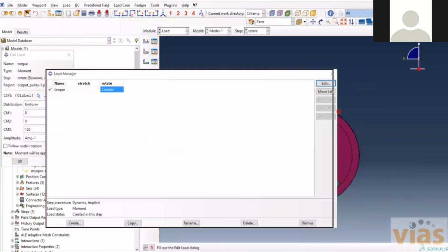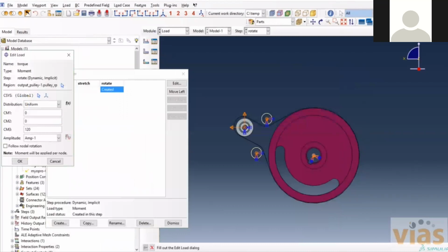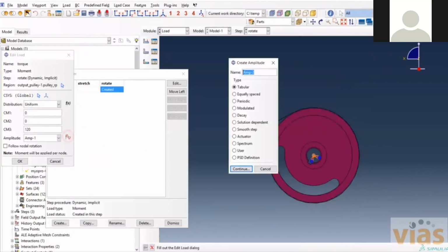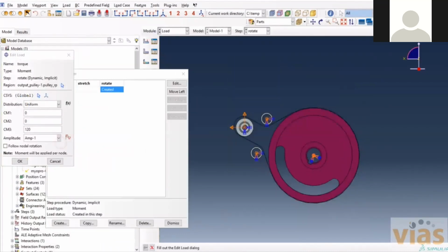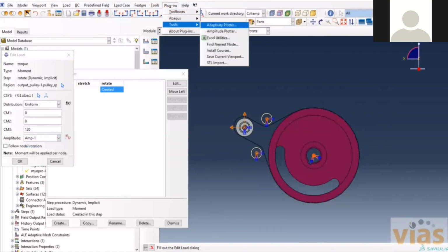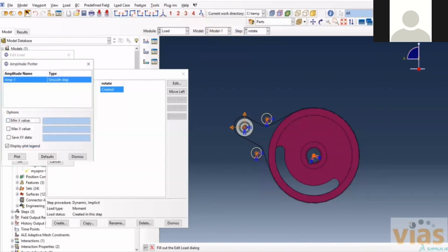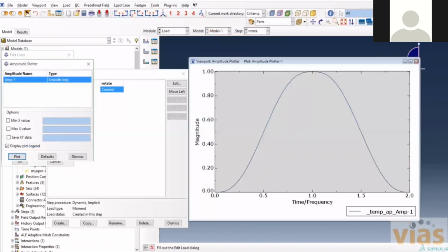Another interesting feature that we've got over here is that the torque or the load that you apply need not always be linear. So we've actually got a non-linear nature that we've defined for our torque application. You can see we've got this nice looking bell curve for the input of the torque into the system. And this could look like anything. If you have transient loads, you could certainly define that as a function as well.